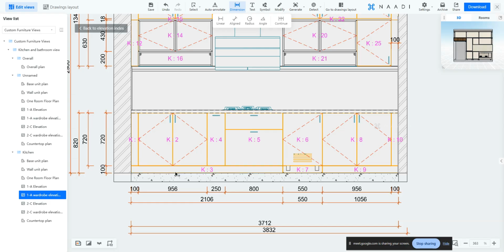And the reason why I made this as 3 separate skirtings in the model is, first thing, obviously, the panel constraint, right? It can't go beyond 2.4. Okay, yes, please be precise on those factors too. So far, as a designer, you would not have considered those aspects. We might just add one huge filler on the entire skirting. Okay, that is fine. But the thing is, we are taking our projects near to production, right? We are moving your project close to production now. So it is better that some basic production constraints are taken into consideration while modeling it.